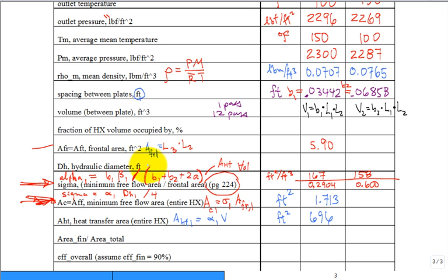There's a little blockage of that finning surface within the passageway. All right, the area of the fin to the area total. What is this area total? The area total for heat transfer. So what you're going to find is what percent of each of those passageways where fluid 1 is flowing through, that can transfer heat, what percent of it is the area that the fin is.